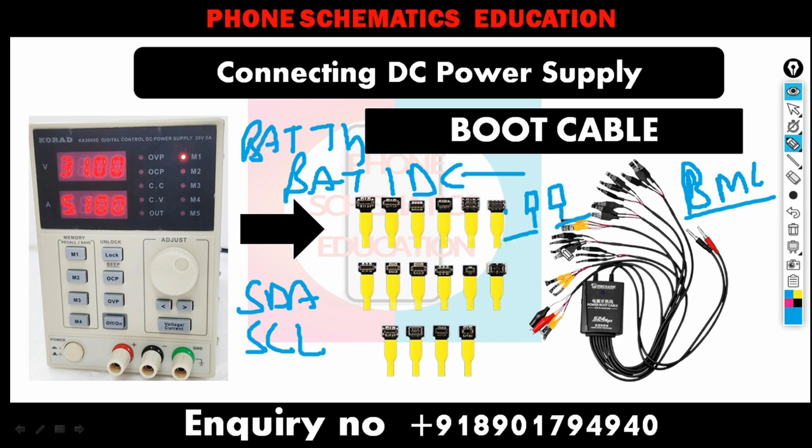So the divider circuit is completed, because in some phones your master IC or program senses the BAT ID line or thermal line divider circuit, and then your phone boots up properly. Mostly with BAT ID, battery identification, the CPU senses whether the battery is there or not.